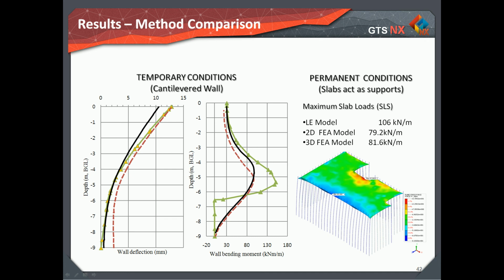It can be argued that the live loads from columns or the surcharge on the active side are for design purpose and can vary significantly in practice. By removing the surcharge and the moment load, the maximum pile deflections reduced to 6 millimeter in the 3D model, which is even closer to what was observed on site, 4 millimeter. Ignoring the instrument tolerance, which is a big assumption due to small deflection, this reinforces the statement that design live loads are not reliable to compare the result of theoretical analysis to field data, unless the design values are controlled and verified. Nevertheless, the finite element 3D model results are closer to the field data available.